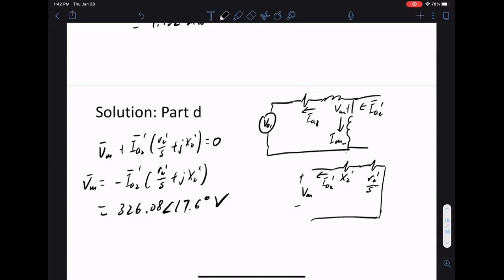Just a quick question. I guess in this case, we can't assume that the shunt inductance is an open circuit because XM is provided. Yeah, so XM is provided, yes. Okay, so if it weren't provided, we could just assume it's open. Yeah, so if XM is not given, then don't worry about it. Just assume that's not there. Okay, sounds good. Thank you.